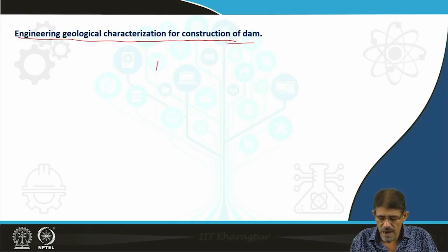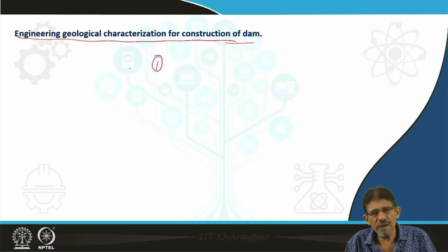Here I am happy to convey that an S-shaped narrow valley having good to excellent rock mass quality is preferred for construction of a dam. However, poor and moderate types of rock in other types of valley require a lot of treatment and preparation and enhance the cost of the dam project in view of future production.